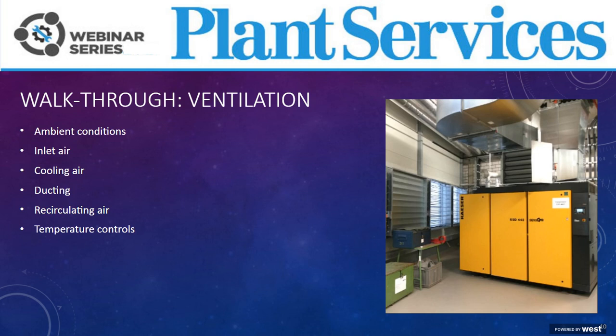Well, now that we've discussed where to install your compressor room, let's talk more about the ventilation within that compressor room. Ventilation should always be a paramount consideration for each compressor and dryer. As mentioned, your compressor is a very efficient heater. In newer compressors, you're looking at upwards of 96% of electrical energy that can be converted back into heat in a heat recovery mode. So if you're not using that heat, it's got to go somewhere. Since your compressors are giving off a lot of heat, it's going to need to be ventilated. Don't forget that your dryers may give off some substantial heat as well, and that should be removed via a fan.